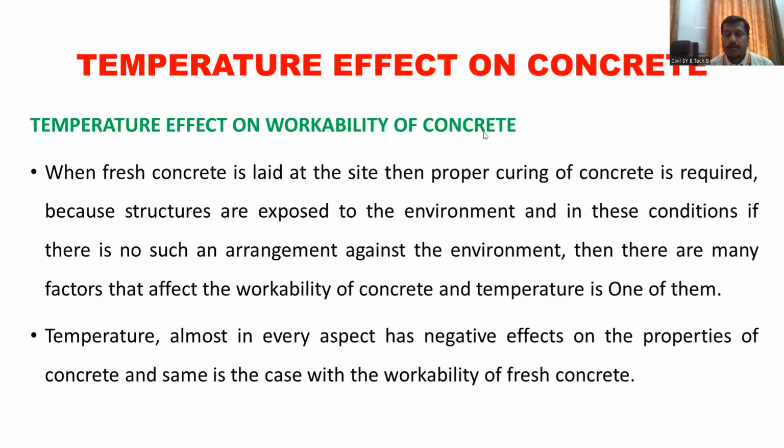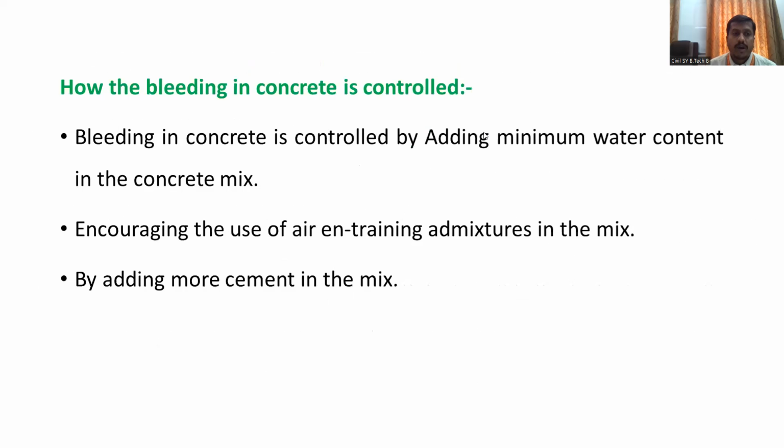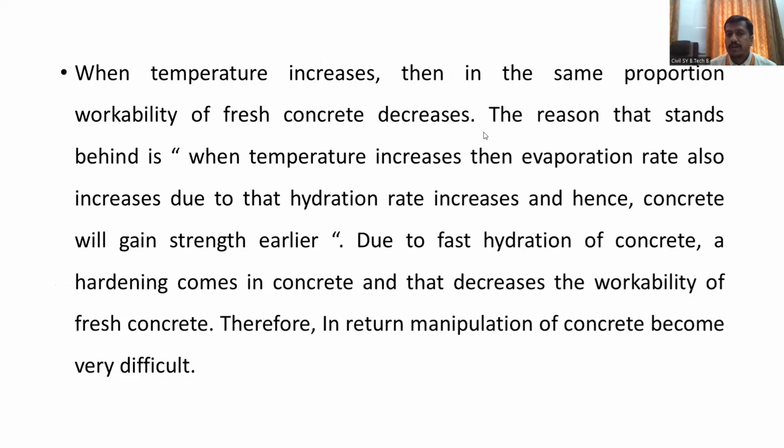So temperature almost in every respect has some positive as well as some negative effects on the properties of the concrete. Okay, and the same is the case with the workability. Okay, now how it affects the fresh concrete, let us discuss. When the temperature increases, in the same proportion the workability of the fresh concrete decreases.